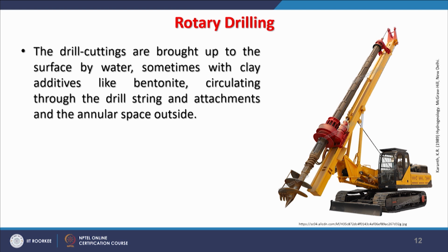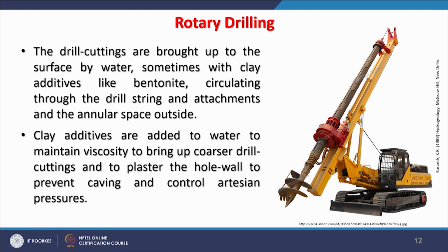So, sometimes water, sometimes bentonite or a special kind of mud is put in, so that whatever is being cut is brought out on the surface, cleaned and kept for reference, and to understand the entire subsurface arrangement of rocks. On the surface you get the lithologs basically.